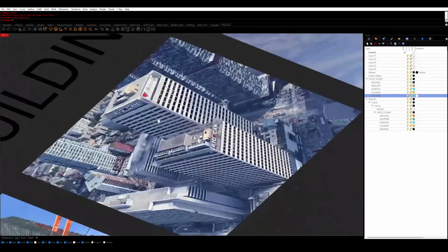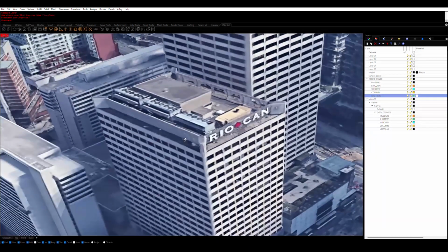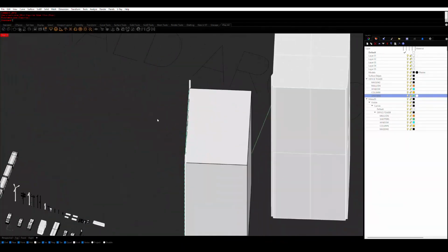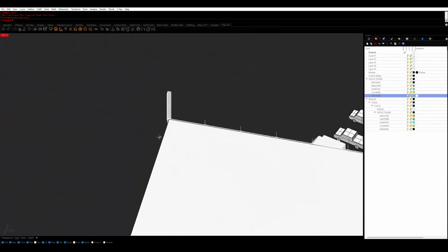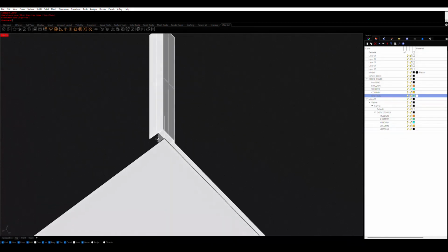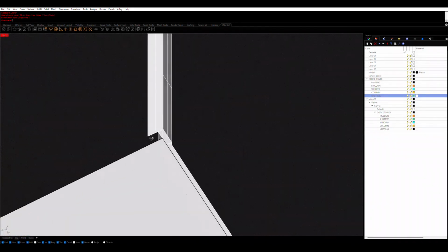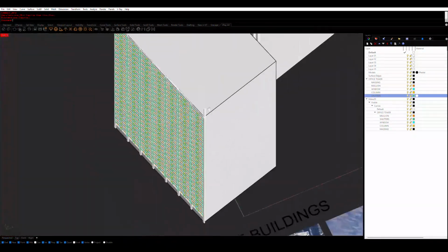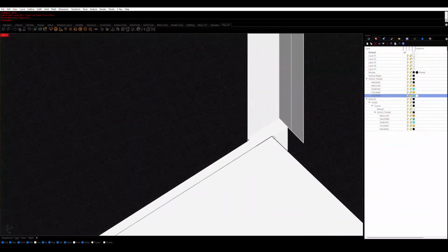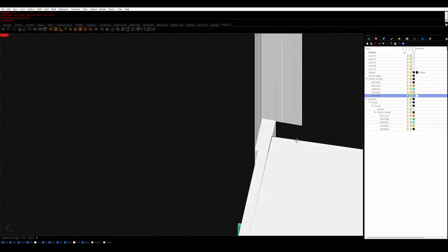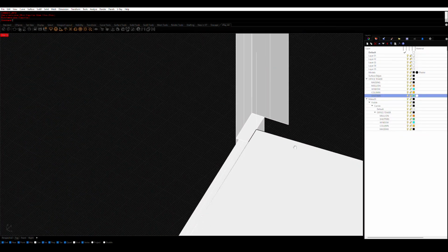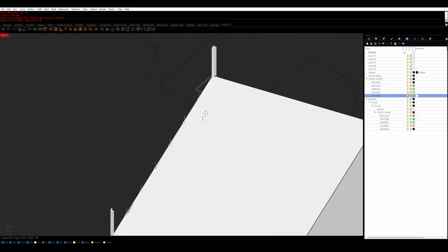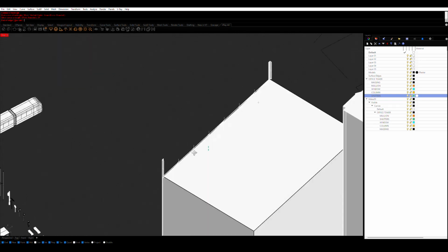And from here, we'll want to make our move towards the center. So before that happens, maybe we want to define our boundary. So if we make a box, let's see. Maybe what we'll start off by doing is to actually create a rectangle. Make this a 3-point rectangle.